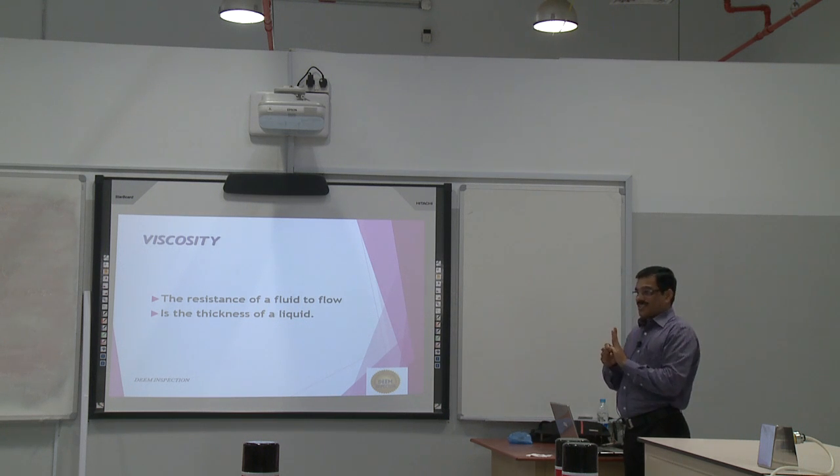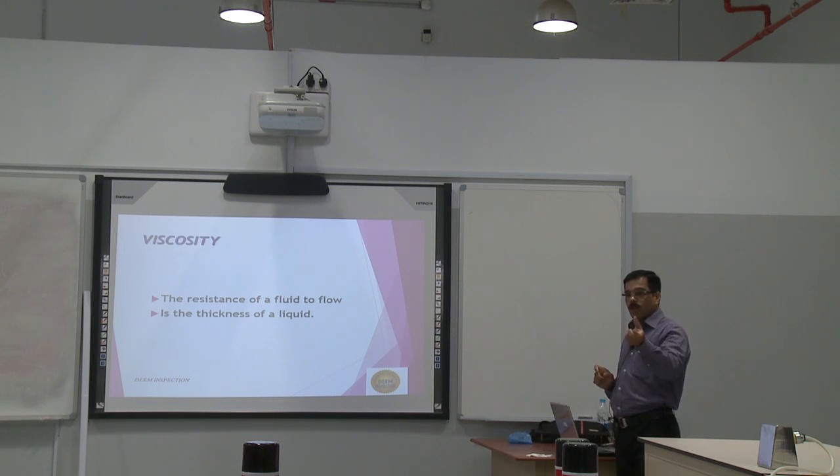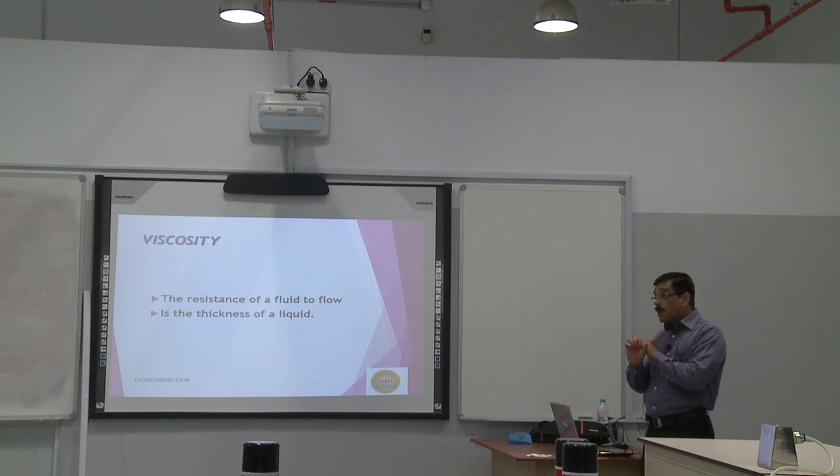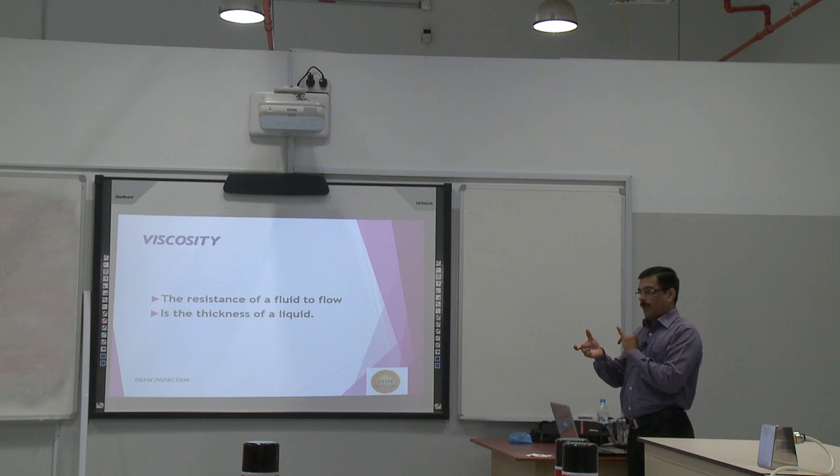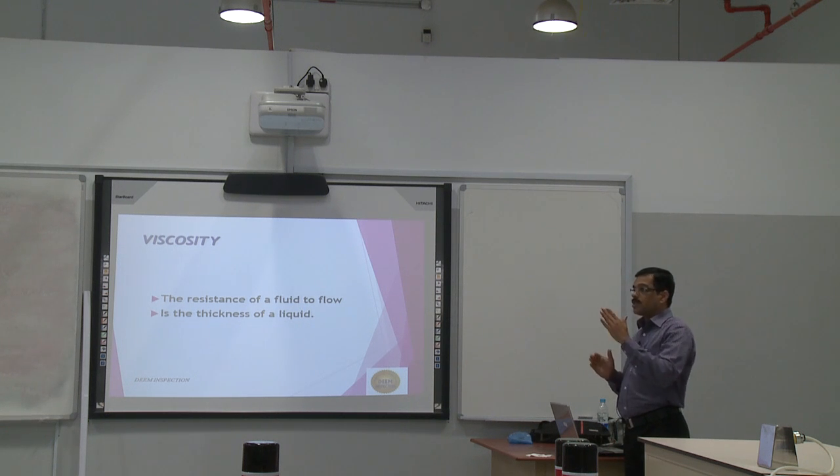To get good contrast, what will we do? We have to use black. But unfortunately, no manufacturer makes black penetrant. For some reason, they are manufacturing only pink or red types. In this situation, the contrast ratio of white to pink gives us more than 10. Below 6 is very difficult, above 6 is okay. So we get almost 10 contrast ratio with white to pink or red. This is the contrast ratio of this penetrant.